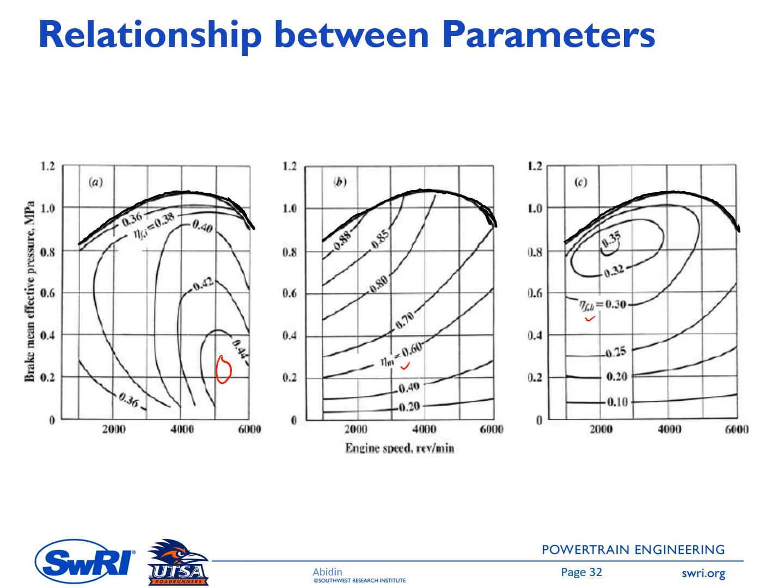Going to the middle, this is the engine mechanical efficiency map. It has a higher number when the engine is operated under higher load and low engine speed. And for sure it will go to 0 as we go to the idle condition.